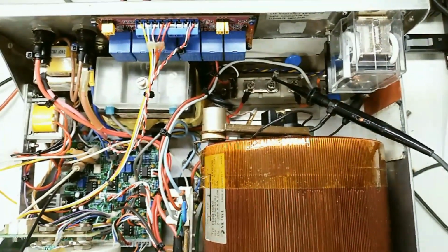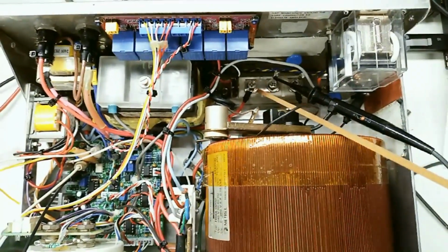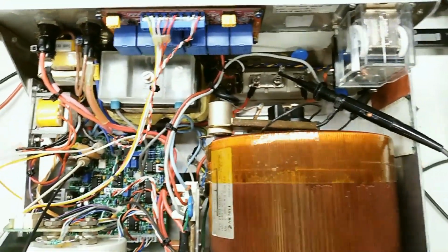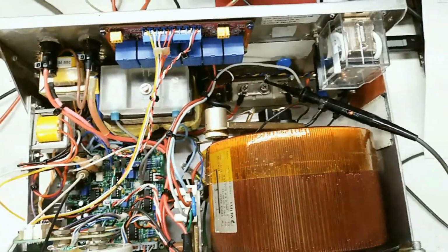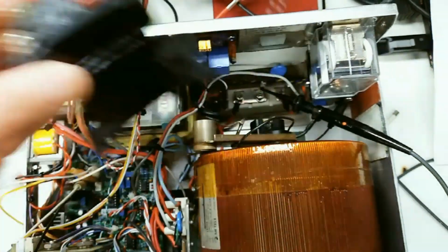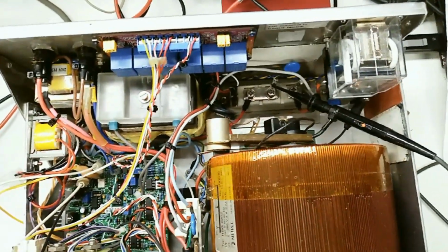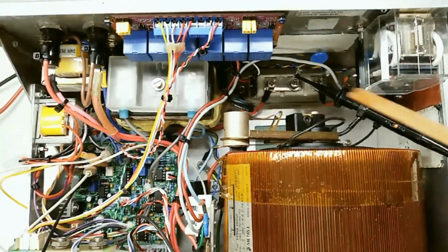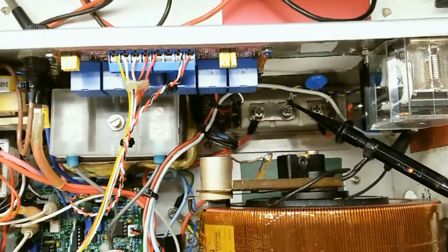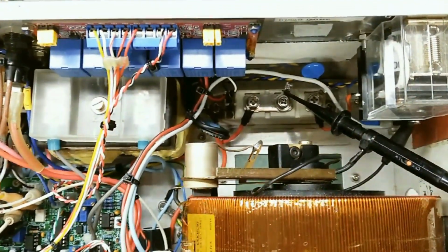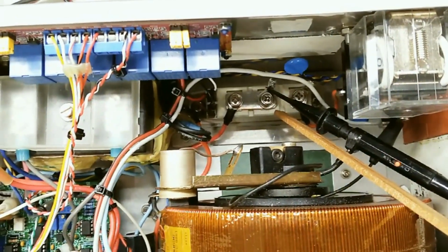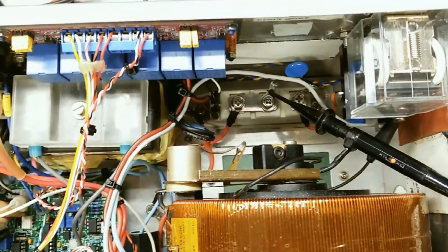Okay, so here I have fitted the two SCRs back to back instead of the triac unit that I had, and the triac unit was actually this one here. And I did encounter a problem with running this SCR onto the inductive load, which is the Variac transformer. And the problem that I encountered is that the SCR doesn't switch 100%. So I'm getting a voltage drop, and I'll show you that on the oscilloscope.